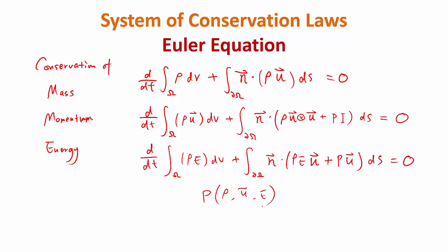So that if you have a different flow, you get a different equation. For air, you can approximate this using the ideal gas law, and there is an algebraic relationship in that. So this equation is closed in the sense that if you have rho and rho U and rho E, and with this algebraic relationship, you can compute the value of the flux of all these three equations. You don't need anything else to solve this equation. This is all you need to solve this equation.